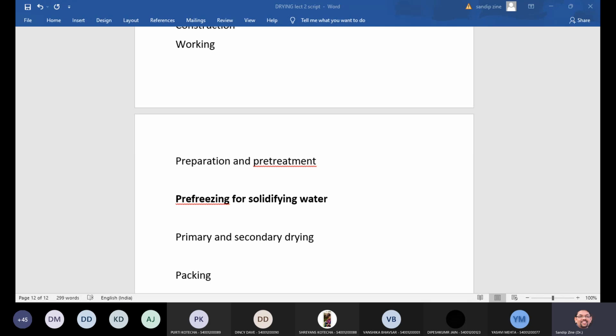The pre-freezing method and the final temperature of the frozen product can affect the ability to successfully freeze the material. Rapid cooling results in small ice crystals, useful for preserving structures that will be examined microscopically, but it produces a product that is more difficult to dry. So you can adjust the cooling pattern or cooling rate even in the pre-freezing point.